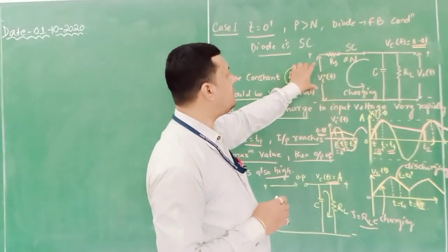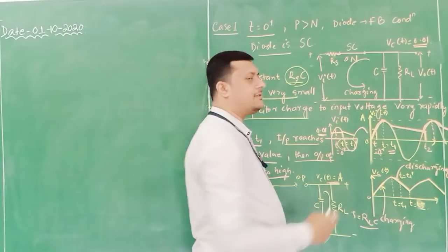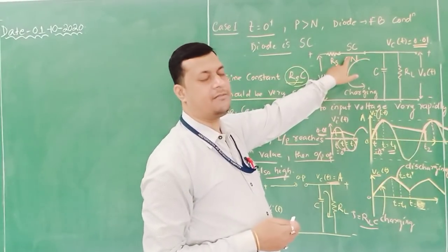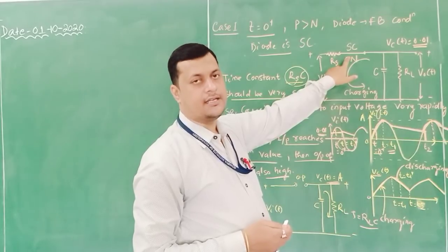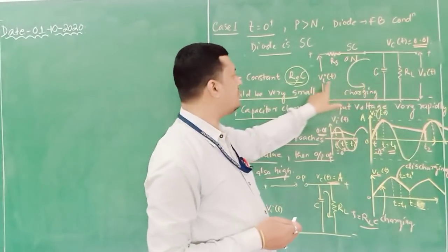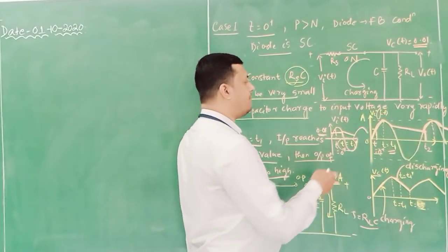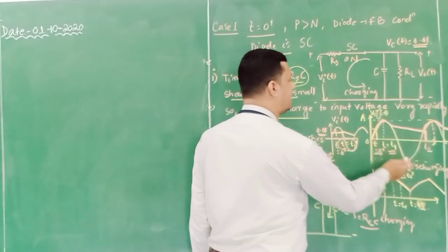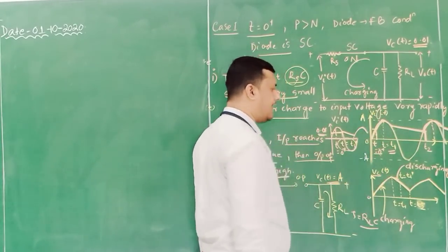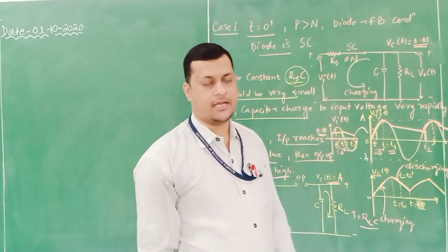When the input signal is provided, the current will flow and cross through this capacitor. When it is switched on, it becomes short circuited. At that particular time, the capacitor will charge up to the input potential. Now, the input potential we have provided is a sinusoid signal, with peak amplitude from plus A to minus A, and these are the two complete cycles we are identifying.